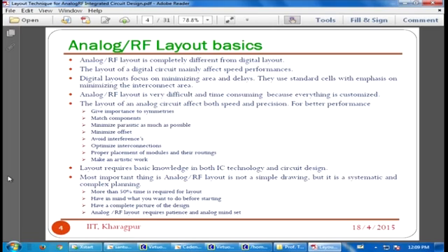So that's why you have to think properly how to make the design, so that the distance between input and output will be less, and it will create less capacitance, less parasitics, and less inductance. Suppose the metal length is more, inductance will come. Parasitic capacitance will come across that resonator, and it will create some oscillations. So extra parasitics, resistance, extra poles and zeros will come, and the circuit performance will degrade.